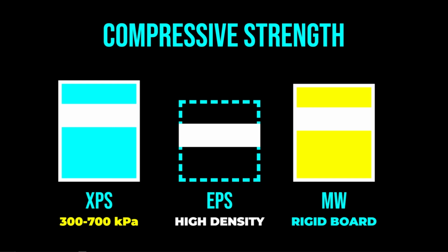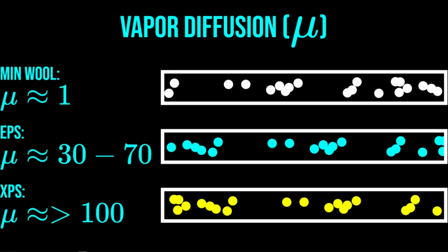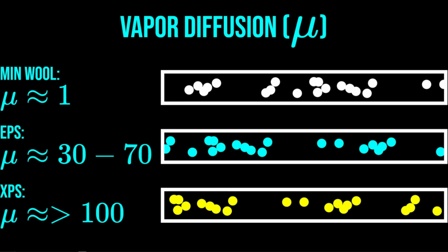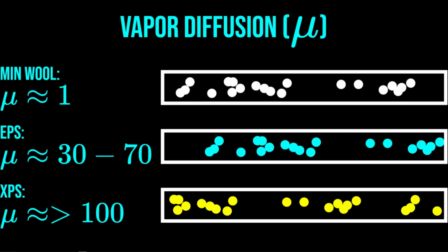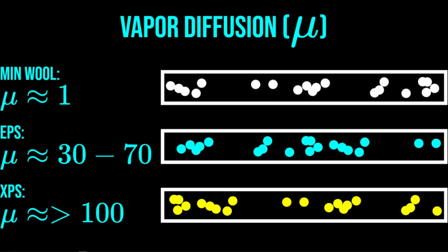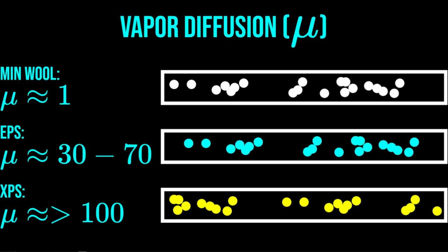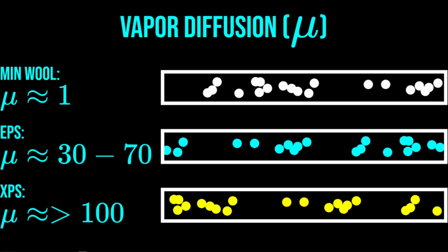Mineral wool is comparatively soft in its flexible batt form, but high-density boards are engineered for flat roof applications where foot traffic is expected. In these boards, the fibers are often oriented vertically or compressed into layers to increase point load resistance. When designing for load-bearing scenarios, engineers must account for long-term creep, which is the gradual deformation of the material under a constant load over decades of service life.